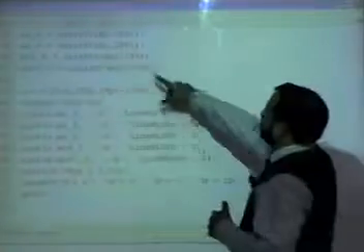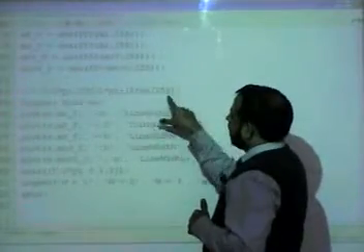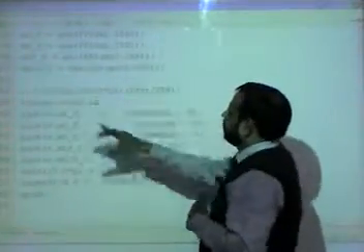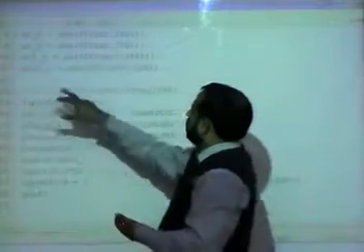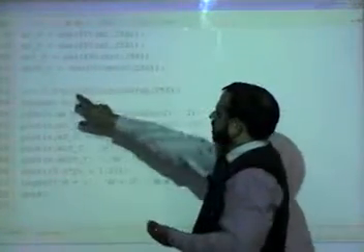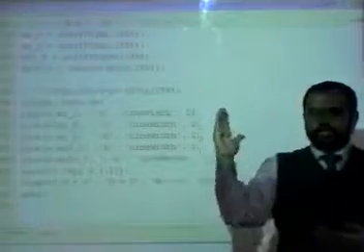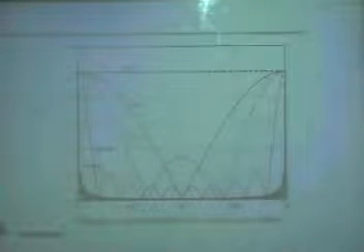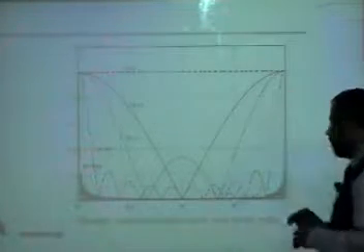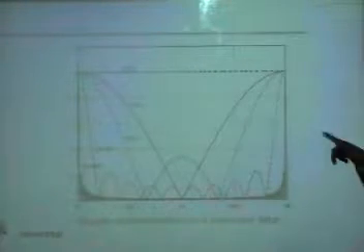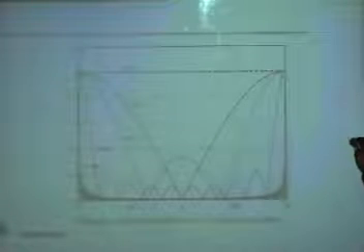This is how it is done: if there is a 256 point FFT, you divide 2 pi by 256. So the axis goes from 0 to 2 pi with this increment. That will make a V vector. It's just a matter of spending a little more time on this. Just do that to figure out how you can re-mark your axis from 0 to pi and pi to 2 pi.